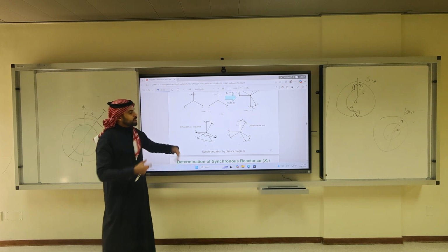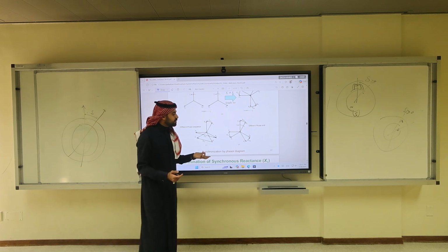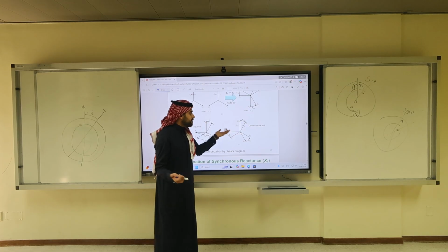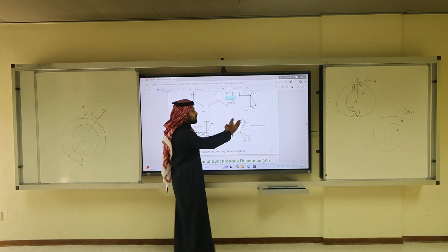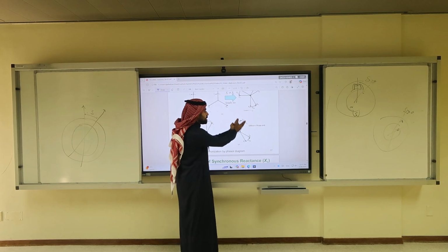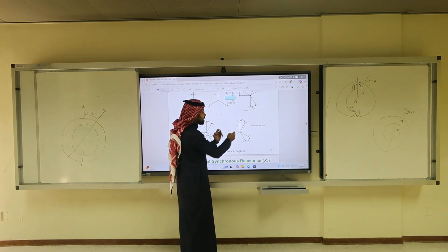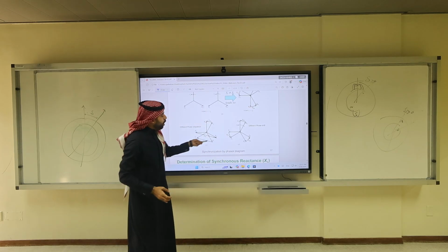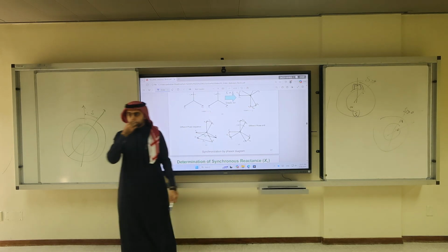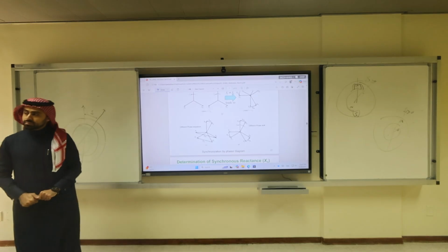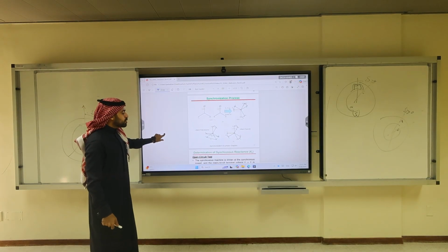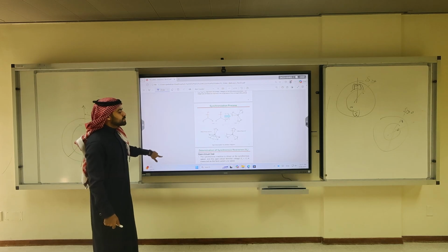Another thing is, if I have a different phase shift, even if I have the same frequency, I'm going to still have a deviation between the small a and the capital A, the small c and the capital C, and the small b and the capital B. All of them would make the lights flicker. Get it? So synchronization is a very important thing in terms of the machines.